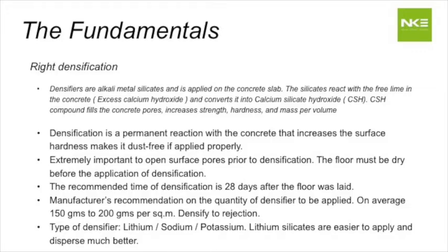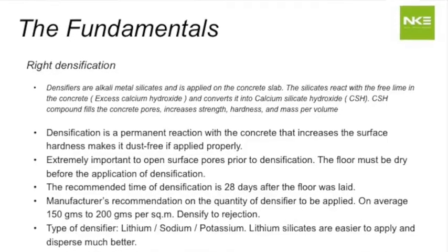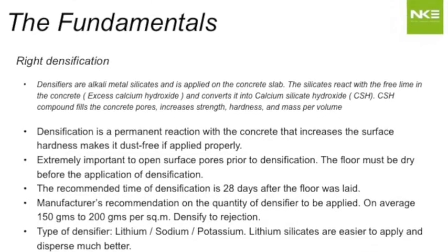The second step is the right densification. So what are densifiers? Densifiers are calcium silicates that react with the free lime in the concrete and create a fresh structure. Now, to react with the free lime, the concrete must first be cured well and must be let to hydrate well. So usually it's 28 days, but depending on different mixes, the duration can reduce. The one who's designing your concrete can suggest that to you.